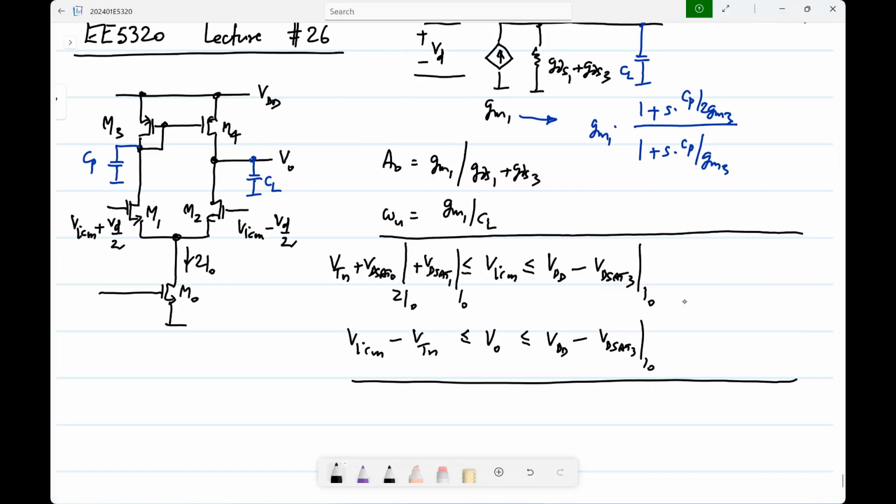So the crude way of specifying the limits of linearity is swing limits. There are two kinds of limits. The limits can come from either the supply voltage or the bias currents that you use. In this case, we are not assuming that a significant load current is flowing, so basically all the limits are related to just voltages.